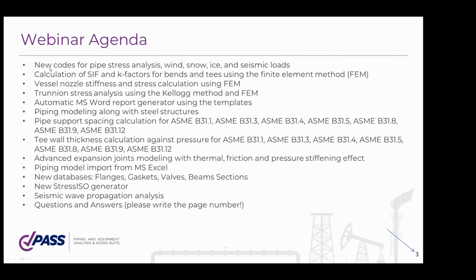We'll talk about the new codes for pipe stress analysis. So it was incorporated into START-PROF software for wind, snow, ice, and seismic loads. Also, we will talk about calculation of stress intensification and flexibility factors for bends, tees, and other elements using the finite element method. Also, we'll talk about the vessel nozzle stiffness and stress calculation using finite element method,